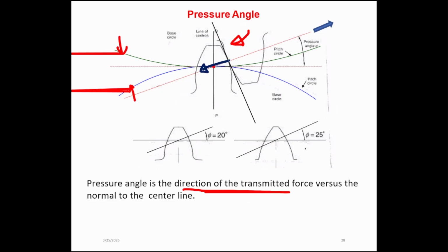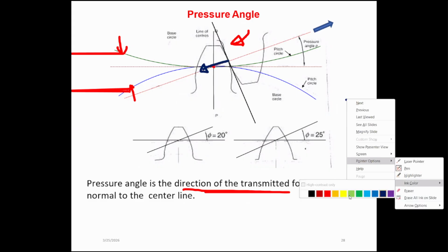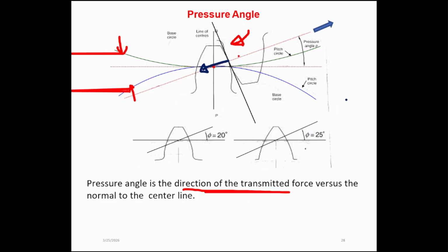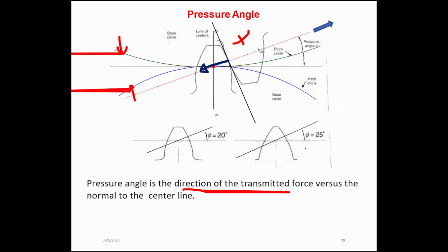So do you agree with me if I draw a line along this red color dotted line? This is the contact point. So I'm pushing this gear profile to the bottom area, in this direction. And according to Newton's third law, there will be a reaction force acting on the gear by the other gear. Sorry, that is green color, right?